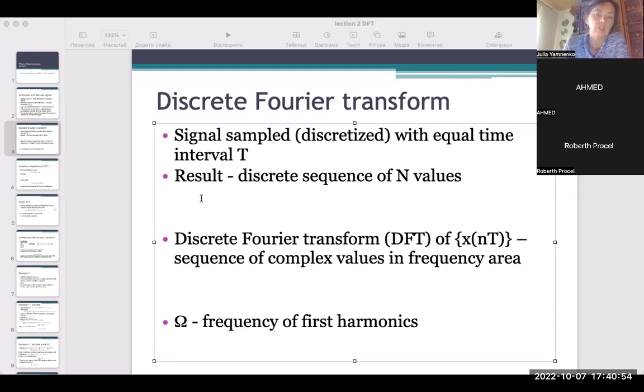We should indicate firstly that our capital N, the amount of digital values, is equal to 4. And we need to calculate, therefore, 4 complex values for the spectrum. It means that the counter of spectrum components k will change from 0 till N minus 1, but because our N equals 4, it will take the values k = 0, 1, 2, and 3.